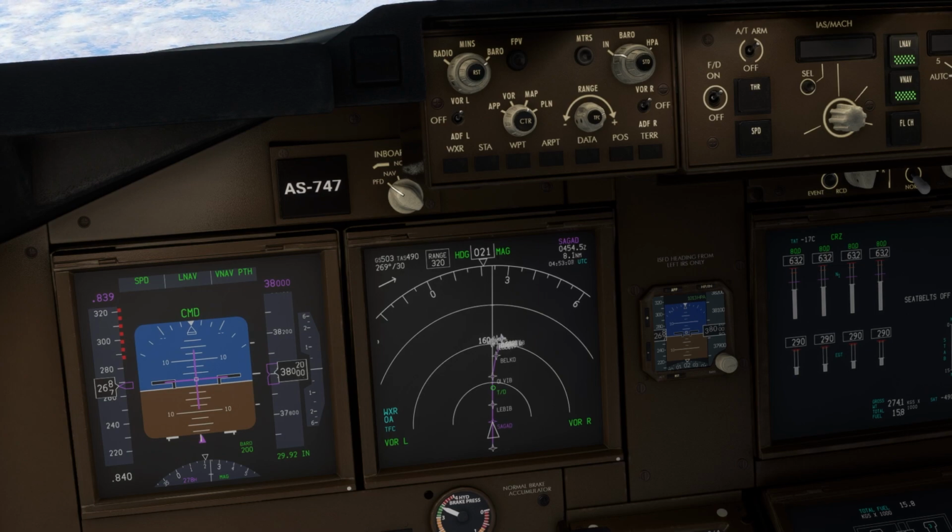This is how the plane, or the autopilot, is calculating the height of the plane. But if you're using radio, then radio signals are basically used to gauge the height of the plane. So it's better to have radio, because radio is more accurate than the baro. But if you're using baro, then you have to enter 1950 over here. You can use this dial to change it, but otherwise it's advisable to use the radio.